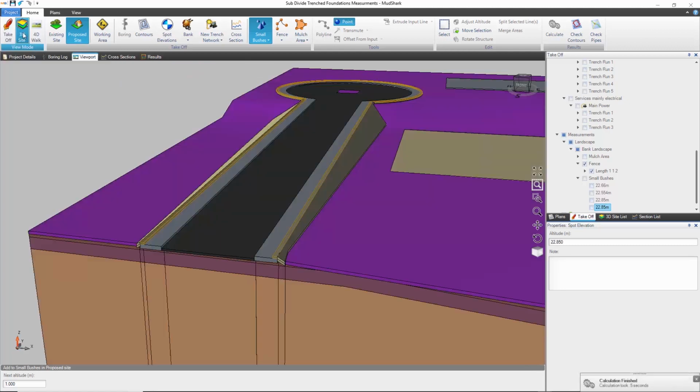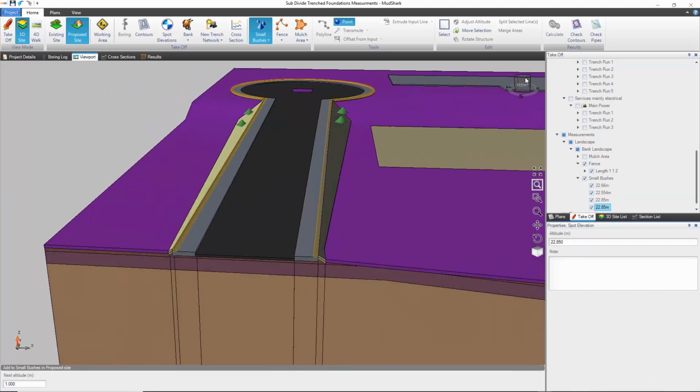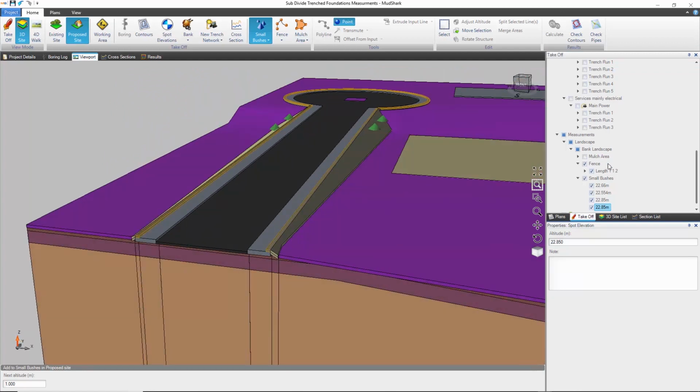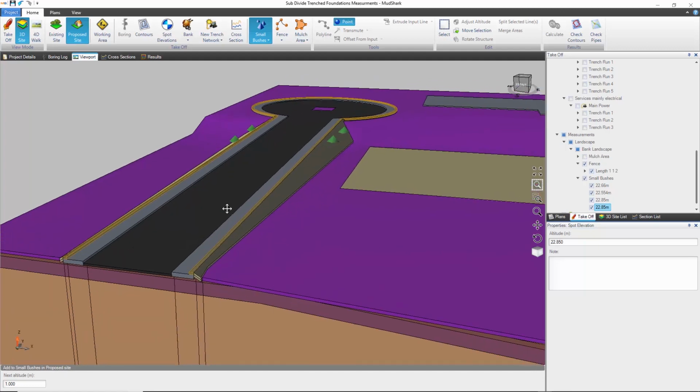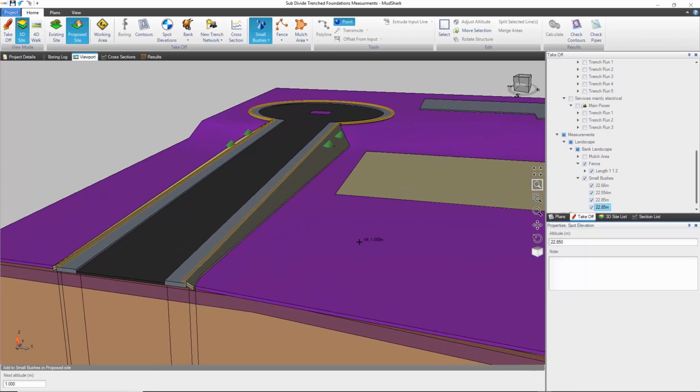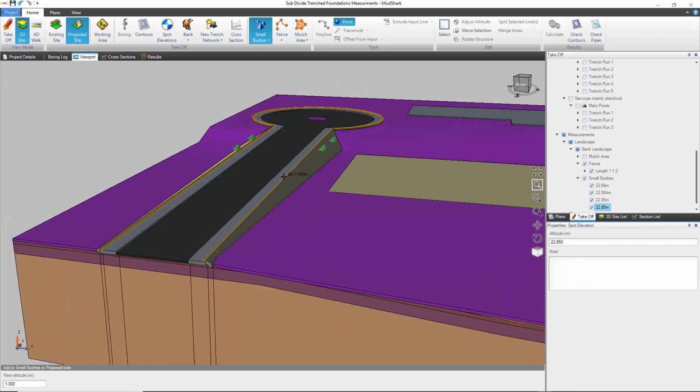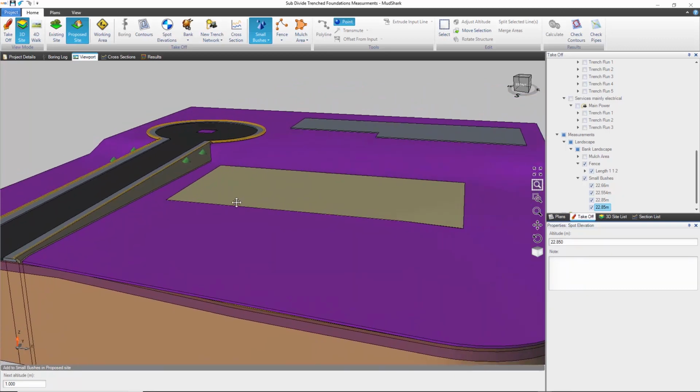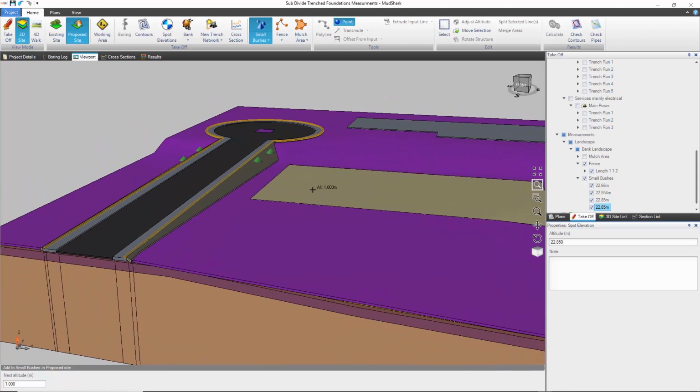And we go to the 3D site and switch our small bushes on. You can see it's overlaid them onto the bank. So for counts it's purely visible, but these overlay options are available for the lengths and areas as well, so you can overlay them across the surfaces. So you can get true surface areas, true positions, much nicer for visualizing and checking your data. So it all helps with the visualization of what you're doing and how it's going to look in practice.